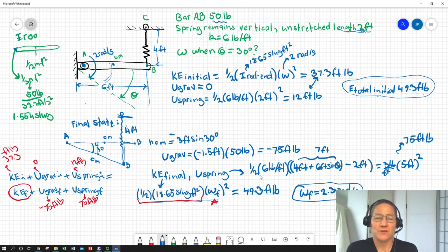So we would have to be more concerned with everything that's going on in the z-axis, and our products of inertia would play a bigger role in looking at the time rate of change of angular momentum. But otherwise, the main points, applications of Newton's second law, are all going to be the same, both for rotation and translation.